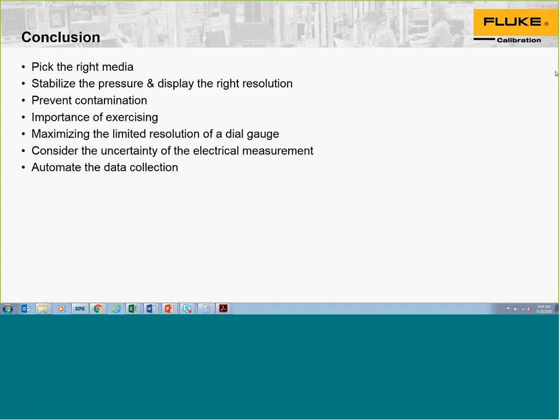Use glycerin for a no-oil calibration of a gauge. Also, can you mix the glycerin with water or alcohol to make the mix more fluid? Depending upon the application, it is possible to use glycerin or alcohol. With alcohol, you need to be careful with devices that have, say, a plastic reservoir, as some plastics react with alcohol. The alcohol will cause them to crack. It is very common to mix water and alcohol together as a calibration media.